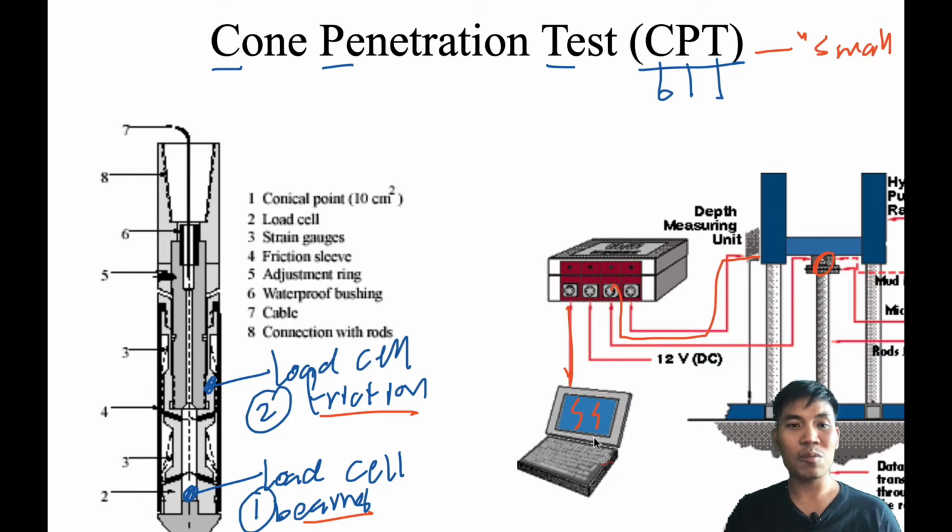And it's not only Suvarnabhumi, there is a new project in Thailand, the so-called Utapao Airport. They applied some compaction to the soil. We use this kind of test to check whether the level of compaction passes or not, and what the relative density of the soil is. We use this one. This one is quite fast.